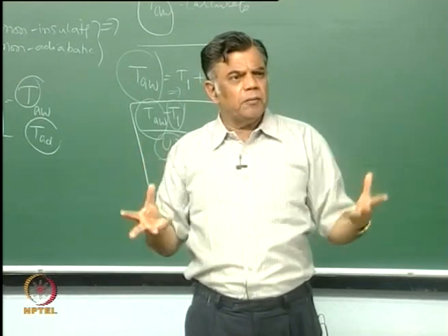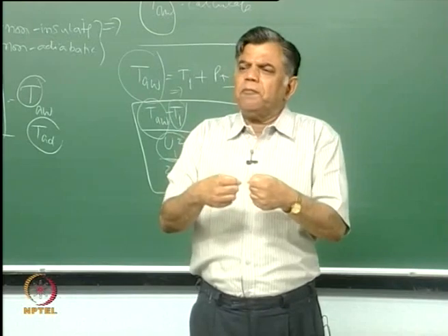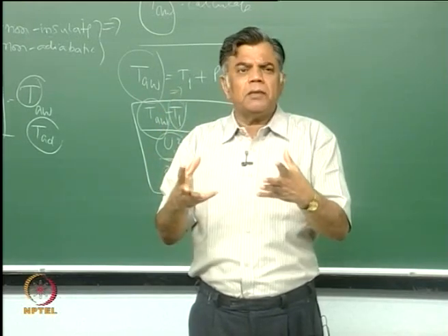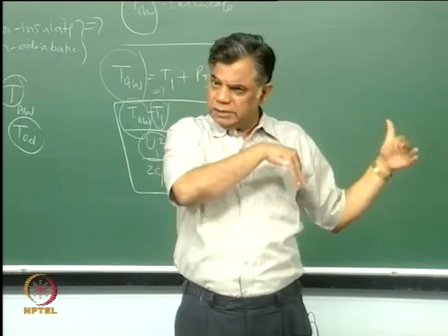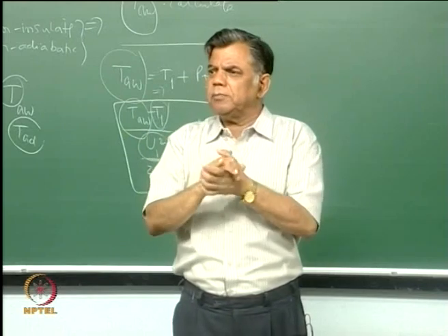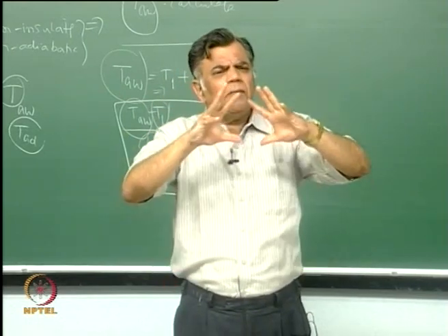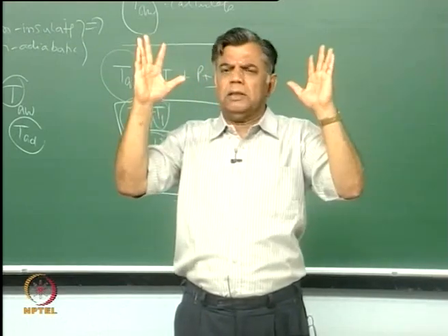You get different temperature profiles, but importantly you find a lot of physics, the effect of viscous dissipation, the possibility that the heat transfer can go to a temperature which is higher than the other temperature in the system, simply because the fluid has increased temperature. A practical application is in lubrication, or anywhere where oil is involved as a lubricant, it loses its viscosity at this higher temperature.